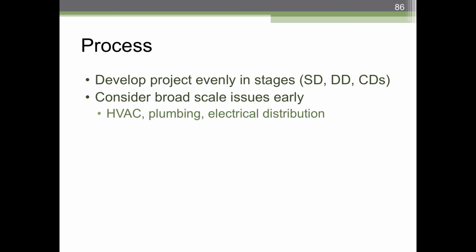In fact, if you use an AIA document, the precision of your cost estimate in schematic design should be within 25% of the final cost. You own that. That is part of your contract if you're using the AIA document, at least one that's not changed. So you have to pay attention. For DD, I believe the standard is within 15%, and for CDs it should be within 5%. And I think if you do a CD cost estimate, which is actually pretty difficult sometimes, you should be better than 5% most of the time, particularly for a public type of project.